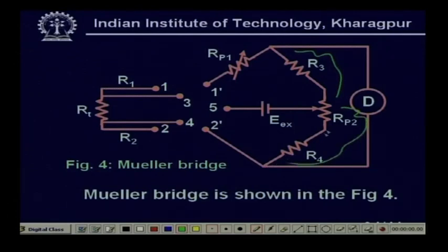That means bridge resistance up to this point should be equal to resistance up to that point. Only then can I write the bridge balance equation. Only in that case will the lead wire resistance be totally eliminated, right. We will find what the different connections are and what the bridge balance equations are. In this case, we can totally eliminate our lead wire resistance problem.